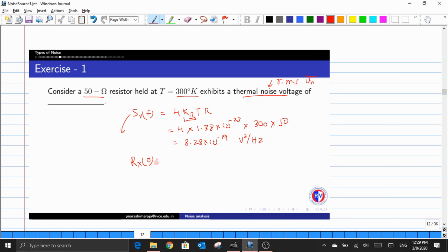the Wiener-Khinchin relation, where the frequency has to be either run from minus infinity to plus infinity or between the set of frequencies F1 to F2. Now in either case there is no frequency term that is given in this particular problem set. So let us assume that we'll use the variance computation of this autocorrelation function, which is an integral that runs between a frequency F1 to F2, integrating over the power spectral density with respect to frequency.